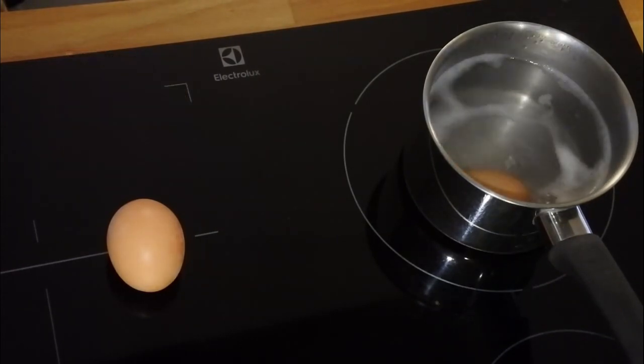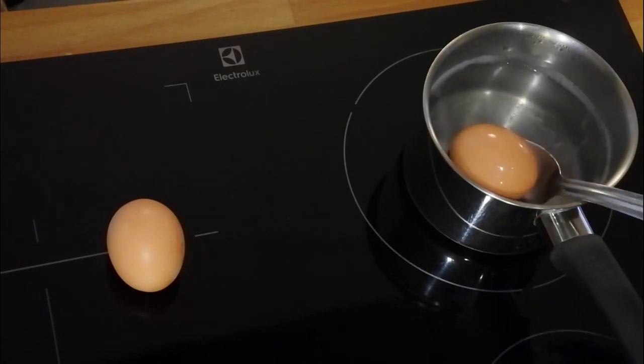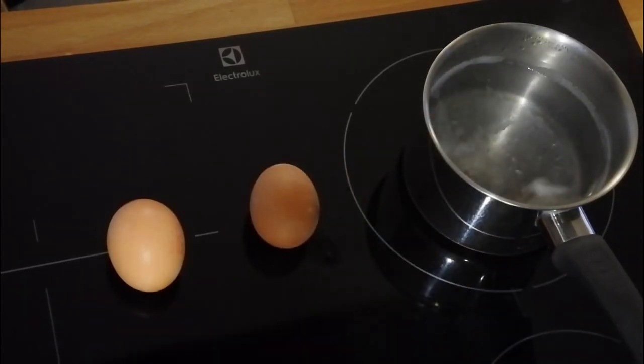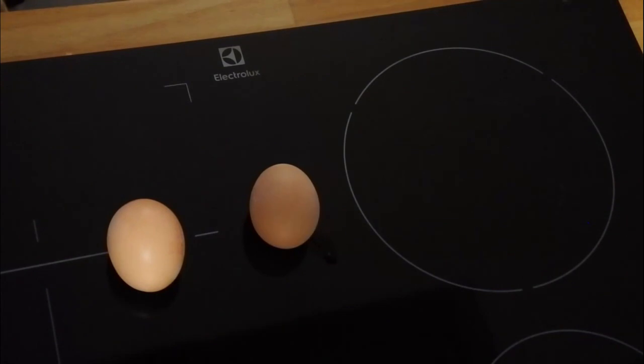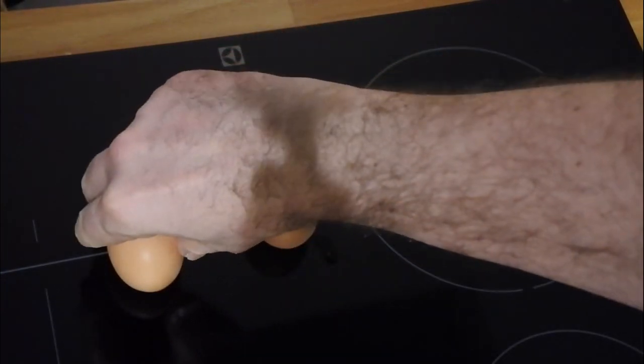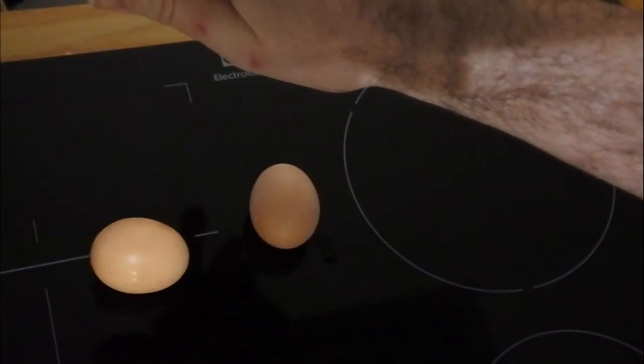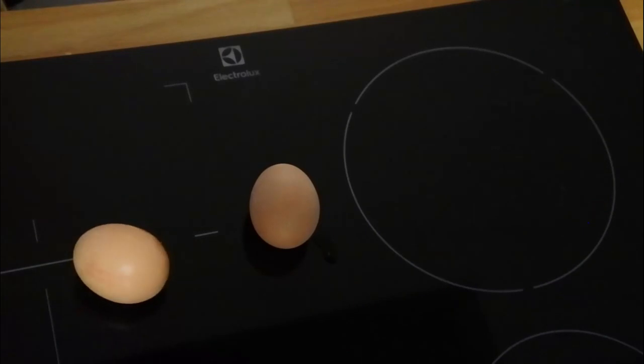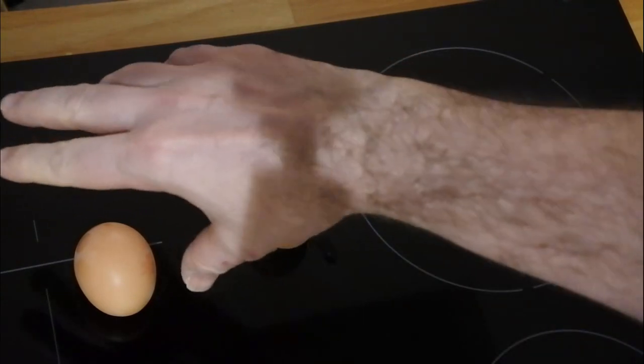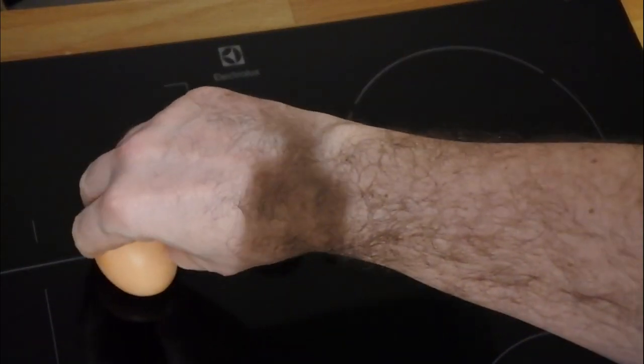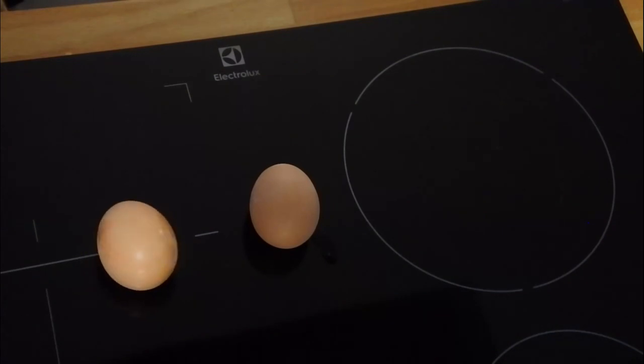Once cooked, the egg on the right can be seen as a solid body, while the one on the left is made of a rigid wall, the shell, with a very viscous fluid inside. If we attempt to impulsively rotate the egg, we create an initial condition similar to the first Stokes problem described above. We see that the raw egg initially takes the given impulse and rotates very gradually as long as the whole fluid inside is driven by shear.